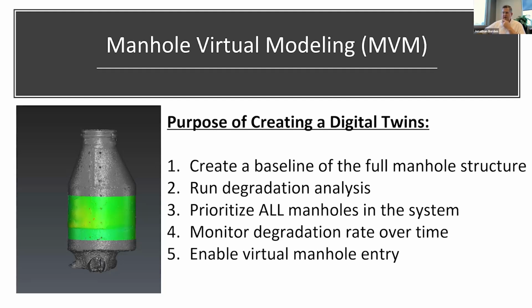Sandra asked the question, can the manhole be 3/4 full to do virtual modeling? I'll go ahead and take that. This does not go below the water line. That said, and I may steal a little bit of your thunder, Jason, I apologize, this same technology can be used for wet wells. It can be used for vaults. It can be used for all kinds of structures. We do a lot of scanning for wet wells where they have to pump down the water, and then we can do the scan while the water's down. So yes, it does need to be above the water line. It goes everything down to the water line. So it needs to be an empty structure, and then we can scan the whole thing.